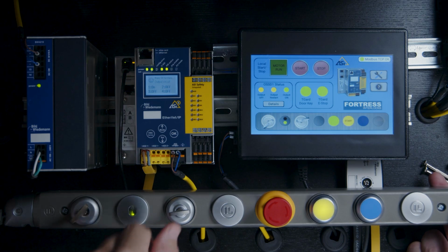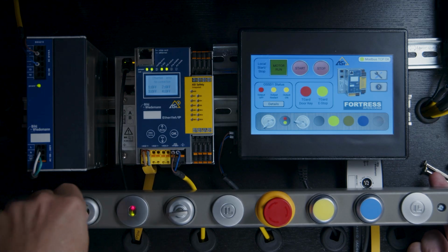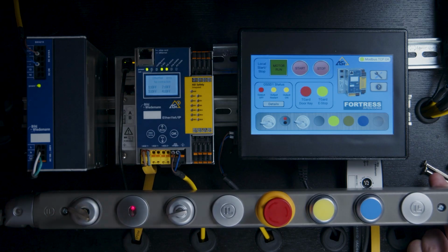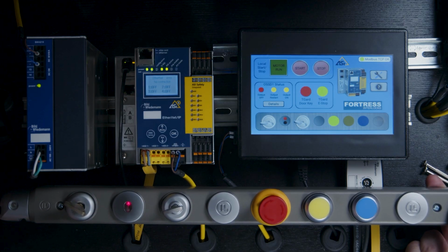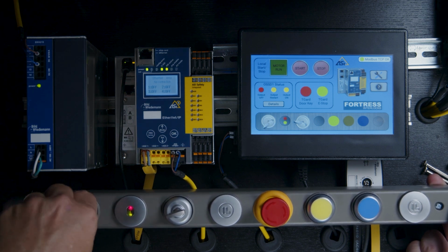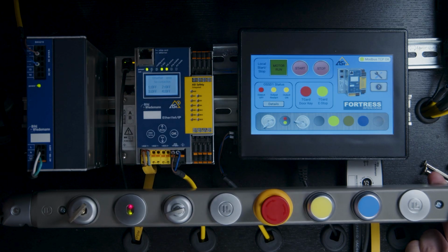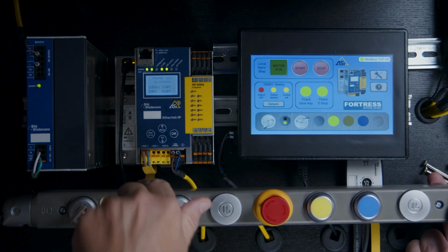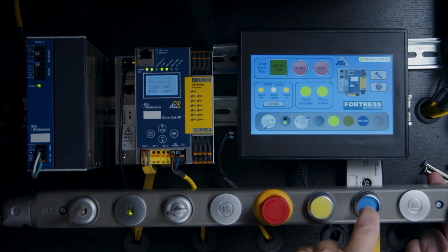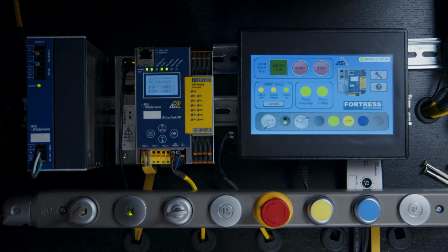All right, if I change my door switch now, you'll see again, my safety output turns off. And if I want to actually open up the door, I then have to move this switch here, and then my door is free to open. Okay, and then I can, again, close the door, move the switch. You'll notice my switch position updates on the screen as well. I'm using the enhanced properties in those graphic objects to take care of that. And then when I move this back to the proper position, we're ready to be restarted, and away we go. Okay, so that's the bench demo that I've created here where we're mimicking the tGard on the screen.